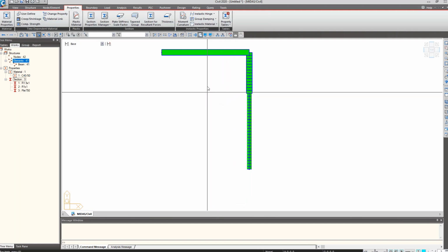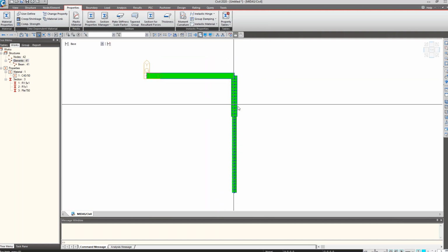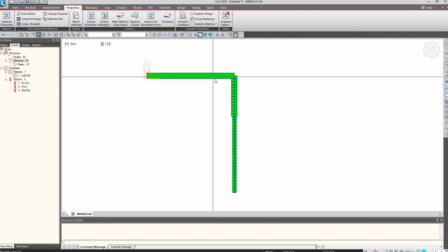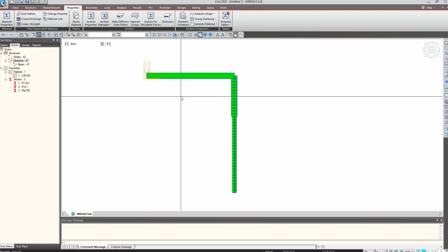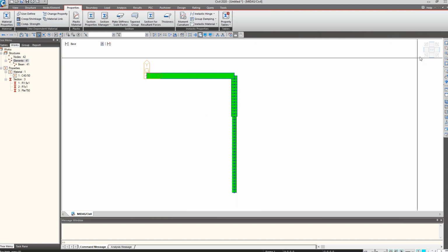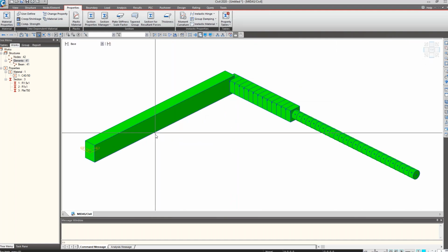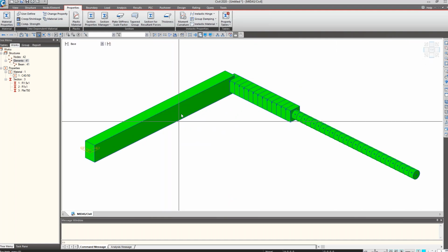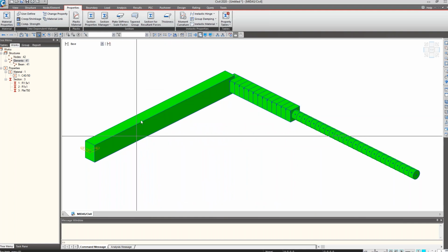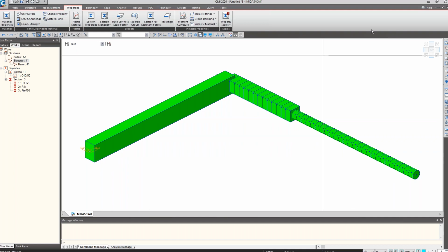Now probably you have noticed that the abutment wall and the deck seem to be the same thickness. That's because we are working on an XY plane. Midas by default understands that when you're using depth of section, it goes in the Z direction. So if we change the view, you will see that the 1.5 has gone through the wrong dimensions. We want to keep the 1 meter as width and the 1.5 as depth.